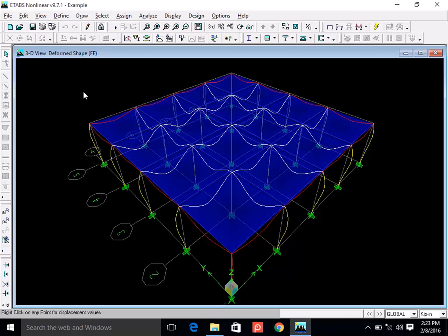For example, we define live load and dead load, partition, floor finishes, and the other one, roof details. So in the new version, you can switch on or off analysis for a specific load case. In the old version, it doesn't ask you for switching on or off analysis for a particular load and runs analysis for everything. So in the new version, you may have a different panel which you can use to pick what load you want to analyze and what load you don't want to analyze.